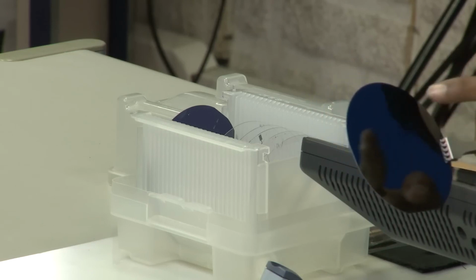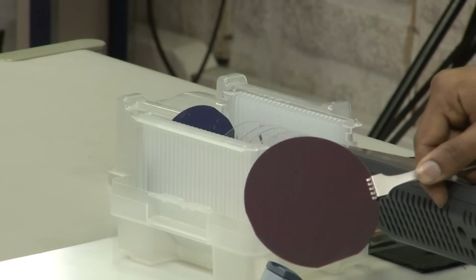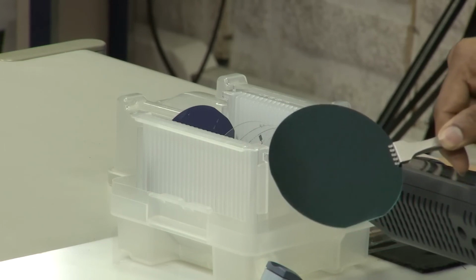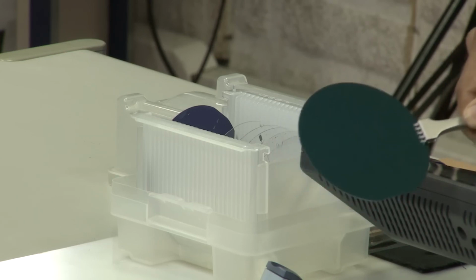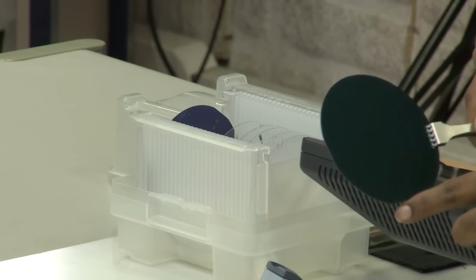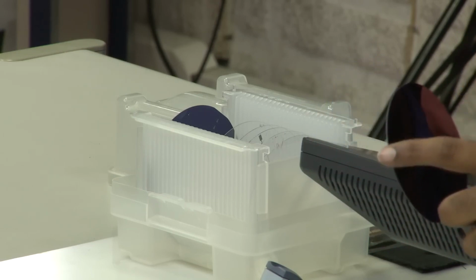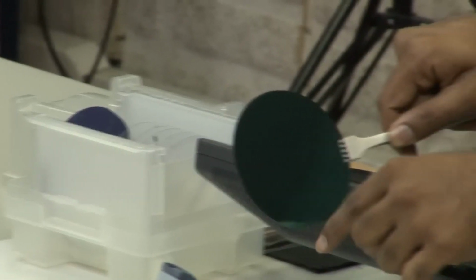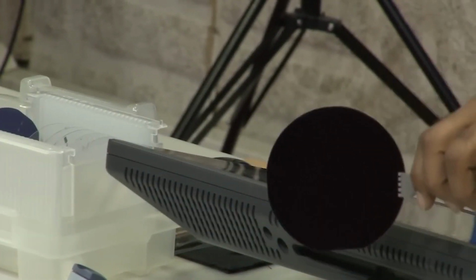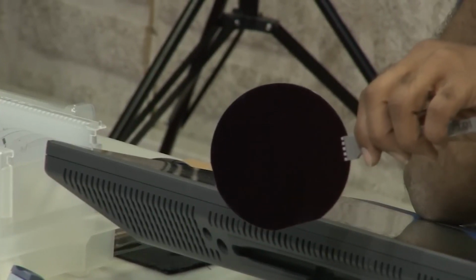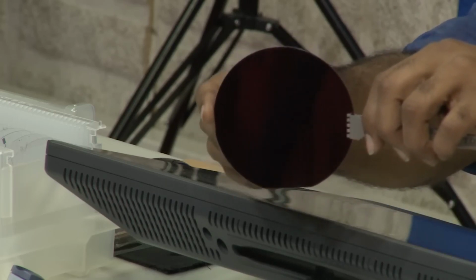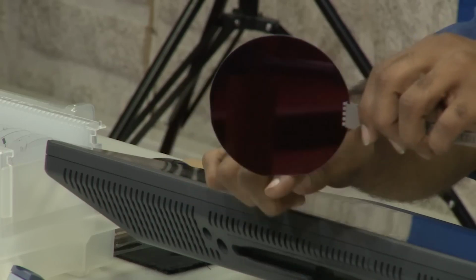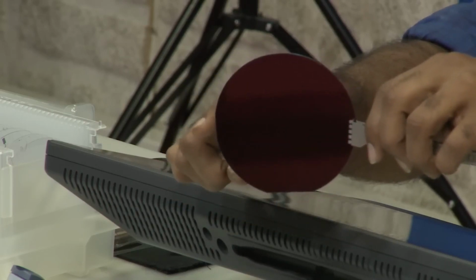And on that I have grown 1 micron of silicon dioxide, you can see the greenish color, right. This is 1 micron silicon dioxide. Carefully look at the wafer, it has 2 flats, one flat is here, second flat is here, alright. If you see, let me show it to you here, it is not completely a circle, right. One flat is here and second flat is here, correct. So, there are 2 flats, this is called the primary flat and this is called the secondary flat, alright.